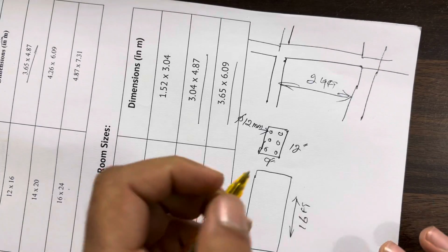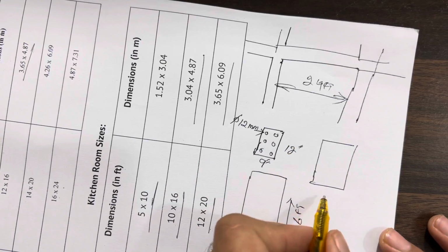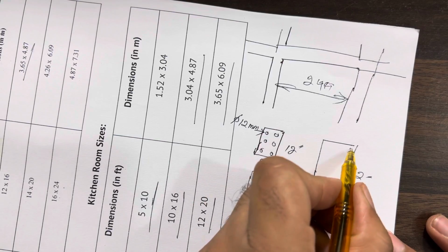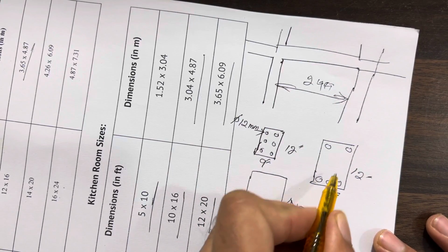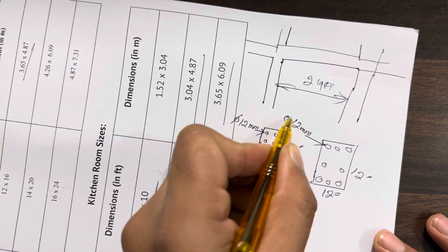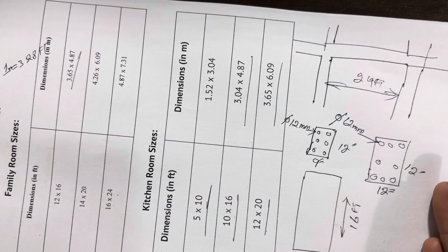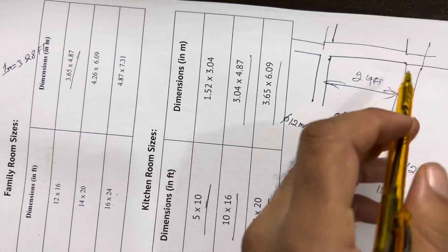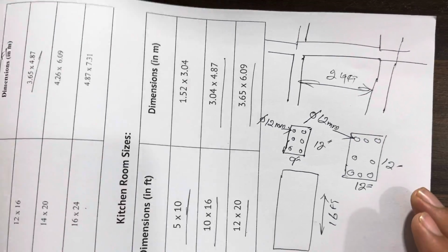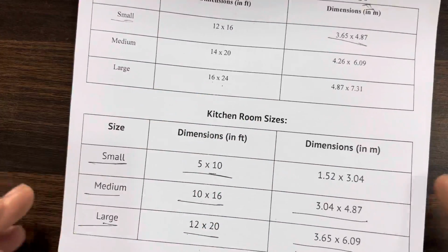But I am recommending you keep the size for 24 feet span 12 by 12 inches. So this is size of column. Inside this you should use 8 numbers of steel rods, and the dia is 12 millimeter. That's because if the span is maximum, inside the beam or slab, it provides bending moment. So for large span, you should increase the size of column, also the size of beam and steel reinforcement, then it can support the structure load of the building. So be careful, especially for this designing.